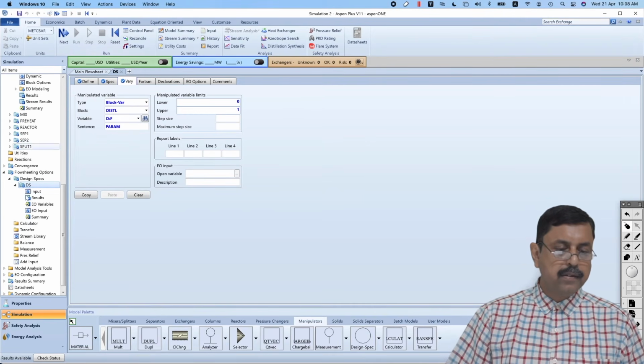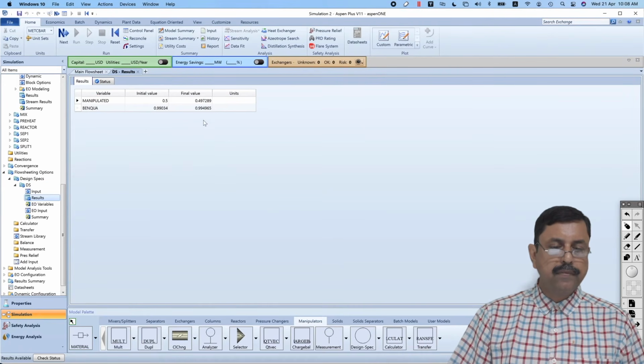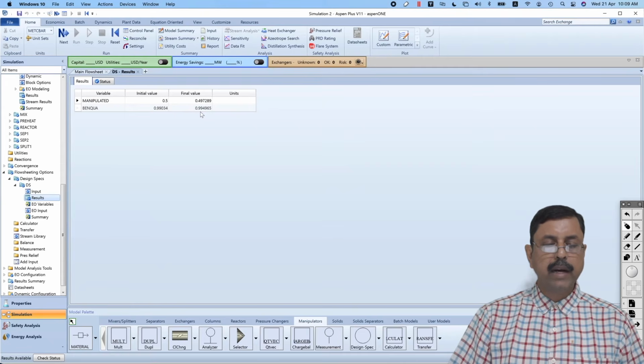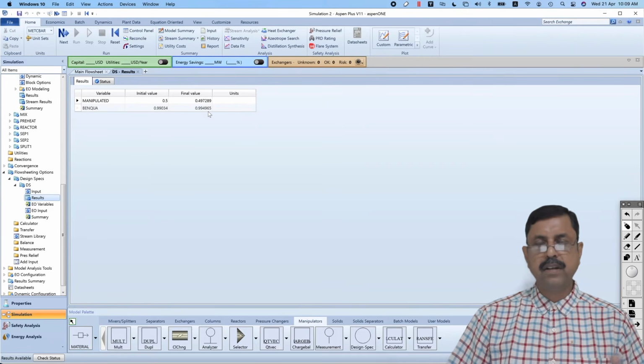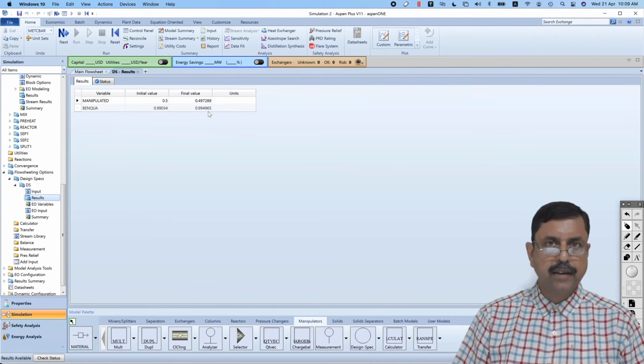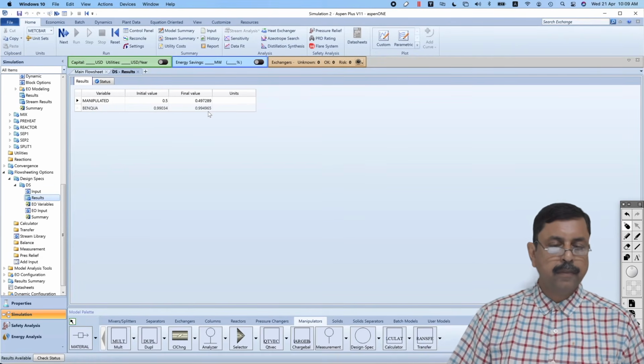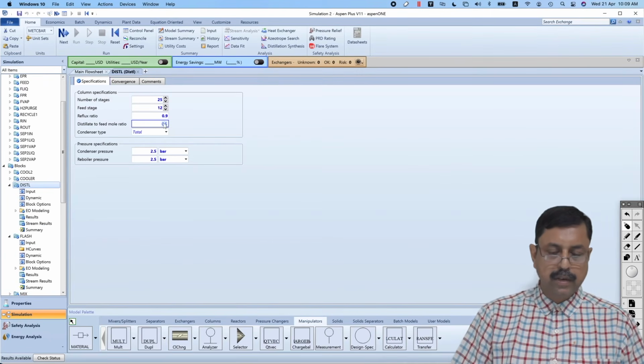Yes, it has run very fast. Go to the result and we'll find the final value at 0.497. So it is very near actually, 0.497289. At that point, we will have 0.9949. We have given 0.0001 tolerance, so we have to accept it. So it is 0.497289. So we copy this number and instead of 0.5 we write